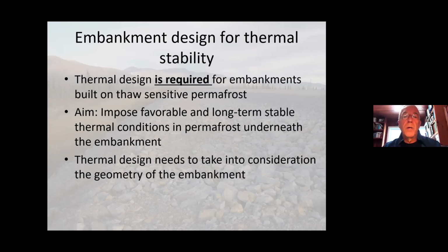So thermal stability, it is clear and unfortunately not always done, but it should be done. Thermal design is required if you're building on thaw-sensitive permafrost. I think it's not very responsible not to do thermal design if you're building on thaw-sensitive permafrost. There can be very important consequences of not knowing what you're doing when you're building on thaw-sensitive permafrost. So thermal design is required. And the idea is to impose favorable and long-term stable thermal conditions in permafrost underneath the embankment.